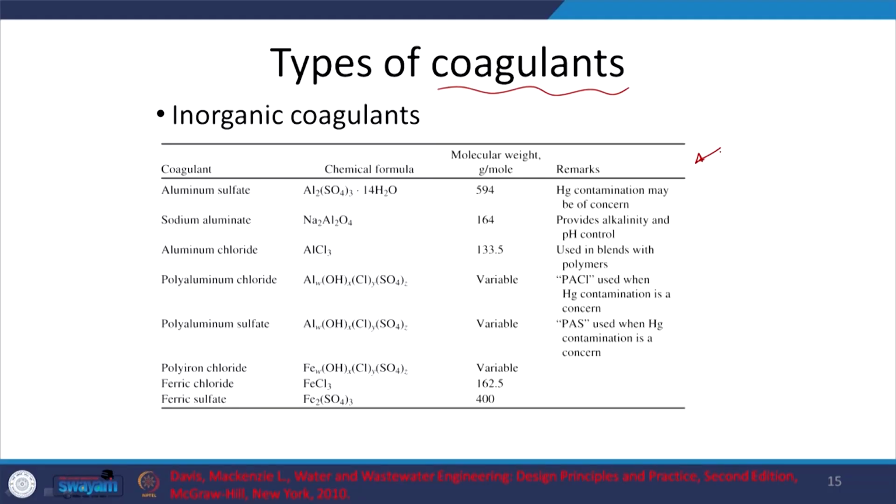So, three major aspects we will look at. Obviously charge neutralization, I am going to add those that have higher charge, Al3+ and such, or Fe3+. But the reason for adding Al3+ and Fe3+ is not only due to the high charge. Why is that? We will look at that later. But as you can see, in general, aluminum, a lot of compounds with aluminum. And with respect to iron, ferric is Fe3+. Again you can see that we are adding the relevant counter ion, but obviously for electroneutrality you will also have to have the anion. So that's something to keep in mind.